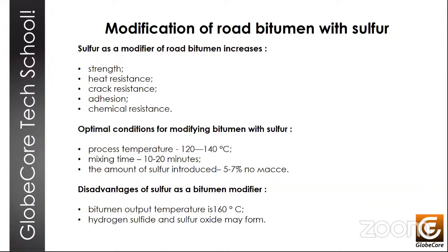And with the addition of elemental sulfur, its content in asphaltenes noticeably increases. The influence of all three factors is noticeable: the amount of added sulfur, the duration of agitation and stirring, and heat treatment. Moreover, physical activation and stirring and heat treatment are somewhat interchangeable to a degree. So the sulfur content in the binder can actually reach 60 to 70% by mass.